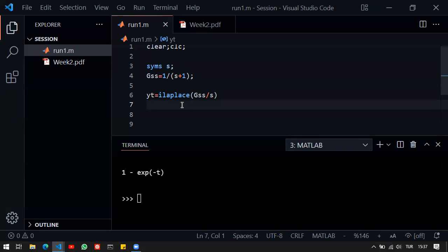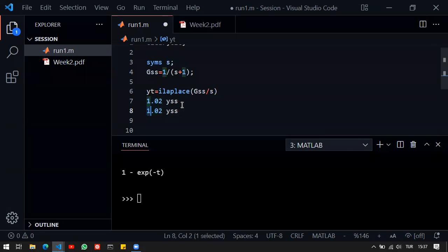And the definition of the settling time is that we have a value in the steady state, and we look for the time instant where the response does not leave the 2% band on it. So 1.02 times YSS, which is the steady state value, or 0.98. So this is a 2% band here. We are looking for the first time instance where we enter this band and don't leave it. So that's basically the definition of the settling time.